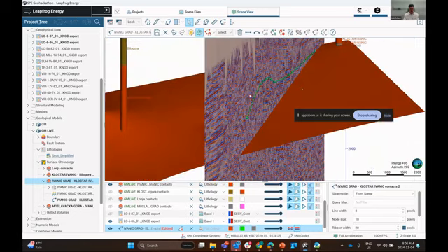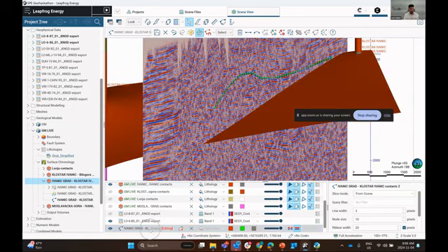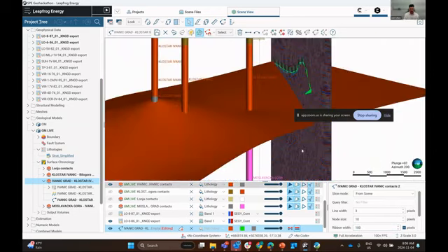The default viewing for polylines is actually quite small. So if you wanted to expand this out to, again, visually QC the interpretations that you make, you can left click in the properties panel and we can increase the ribbon width to something quite a bit larger.